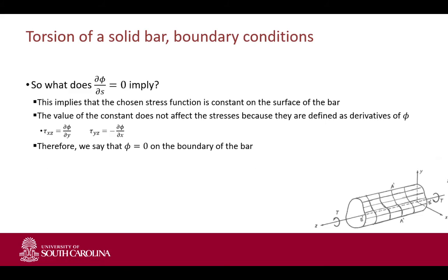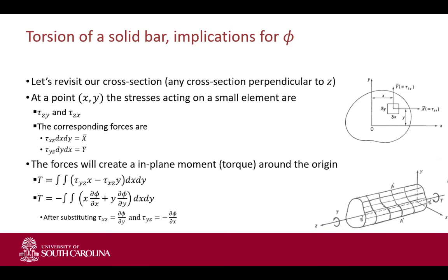So the last step we have to do is, since we are talking about torsion, we want to have everything also related to a torque or an applied moment. Similar to our engineering bending equation, where at the end of the day we turn back into the moments, where we took the integral of the forces or the stresses to create a moment and relate that to an applied moment. We want to do the same for the torsion case as well.